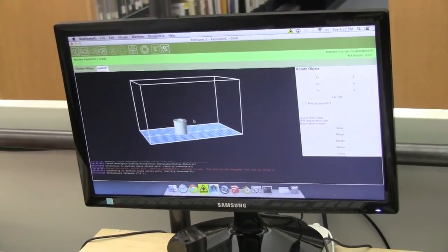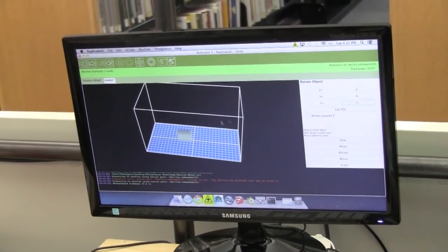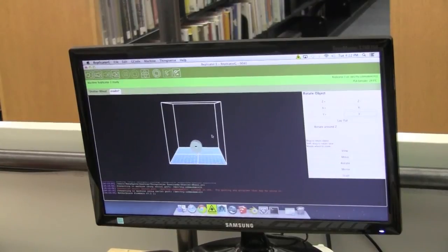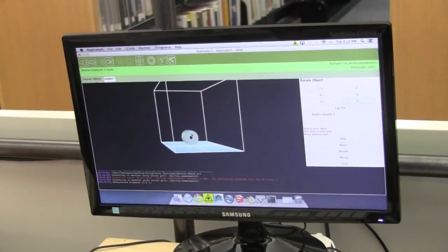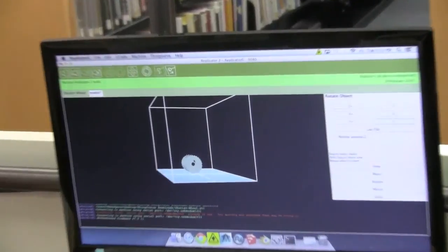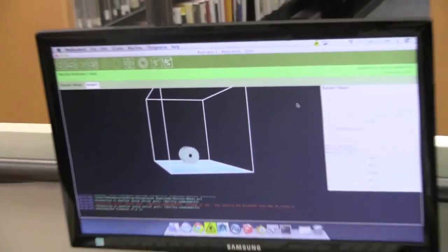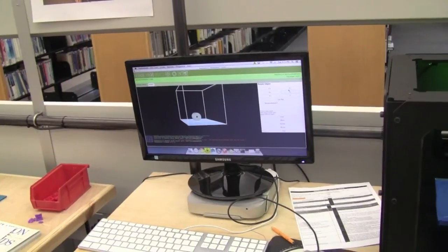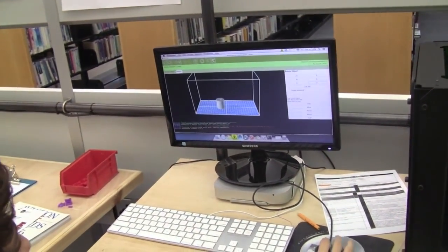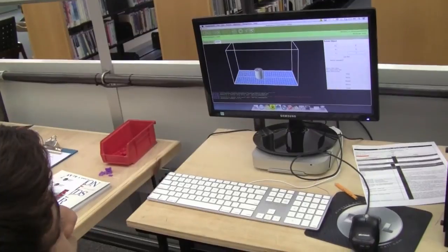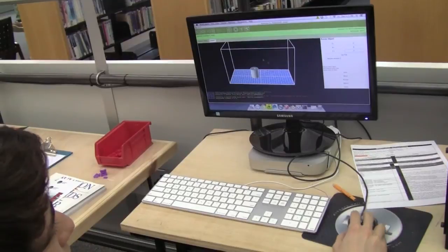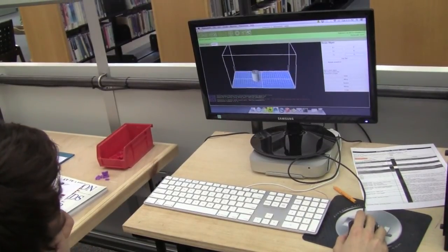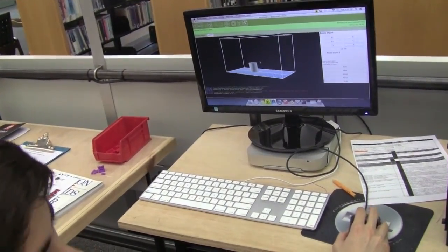The reason why you want to rotate an object is, let's say someone had built the object like this, where it comes in on its side. Obviously this wouldn't be optimal for printing because you have this single point along the cylinder that's going to hold up the entire model. That's not really optimal because it might topple over and it just won't come out cleanly. So then you would use rotate to fix your model. Oops, like that. Generally what I tell people is you want the largest, flattest surface to be touching the platform. This is the only flat surface, and it's touching the platform, so that would be the best way to print it. Okay.